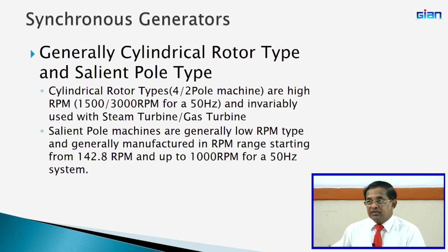But then you have the additional cost of buying the gearbox, as well as maintaining it, including the bearings. Gearboxes have a lifetime of about 10 to 12 years. So, after 10 to 12 years you will have to replace them. So, there is an additional initial cost as well as an operating cost and maintenance cost, and then the replacement cost every 10 to 12 years.